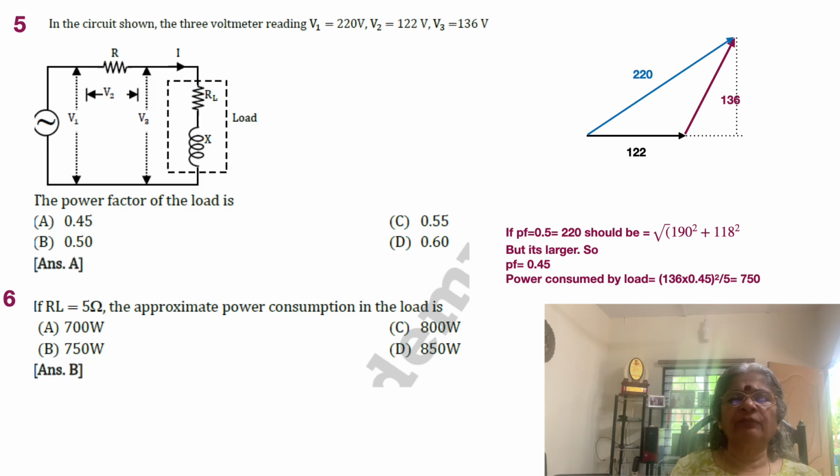We reject 0.55 and 0.6 because they are larger power factors, which means smaller angles. Of course 0.45 is smaller, but you can also use the conventional method to calculate. This is just for speeding up the understanding, as also the method of doing the problem, wherein we have chosen a particular power factor which is easy to assess, because we know that when you have a power factor equal to 0.5, it means you have an angle as large as 60 degrees.